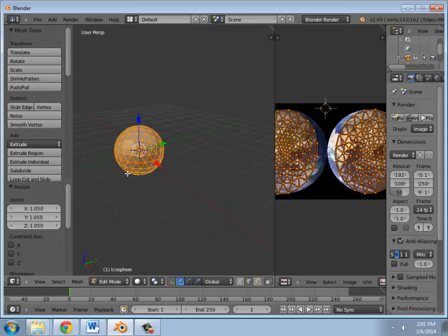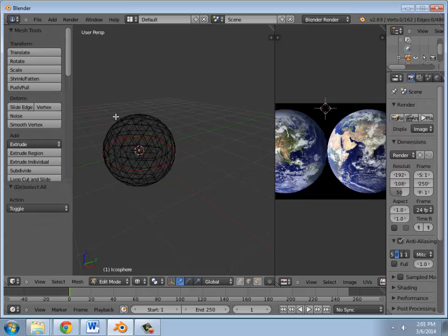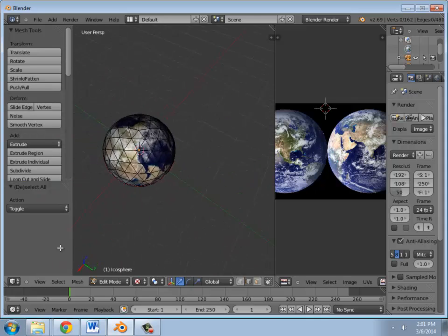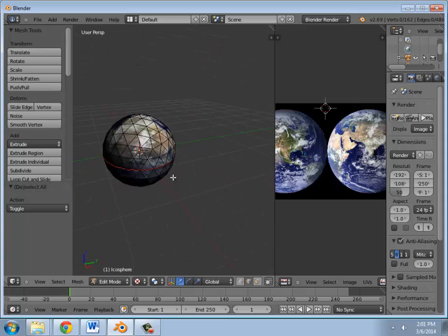Now at the moment, if I'm looking at the sphere, it looks like a gray sphere, which is exciting and all. If you go under here, you may not have known this before, but right now we're in solid mode. Wireframe mode, by the way, lets you look at all of the points without having the solid surfaces in between. Texture shows you the textured surface. Keep in mind you still have to worry about light, so the backside of the Earth behind the light is not going to show up as light.